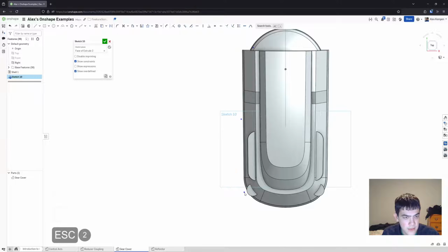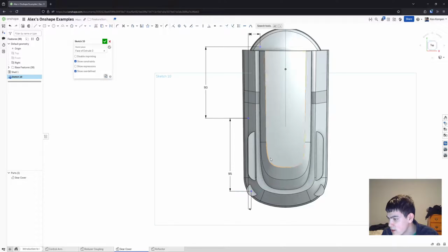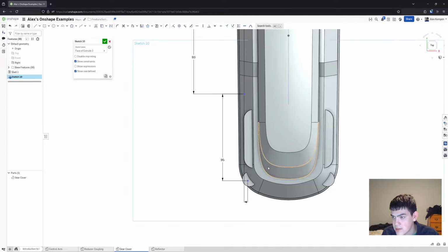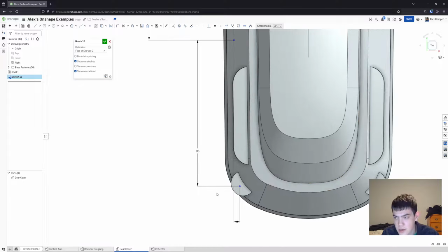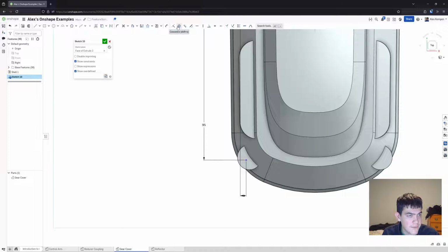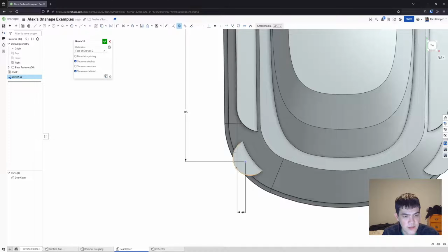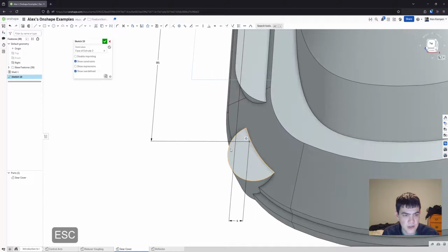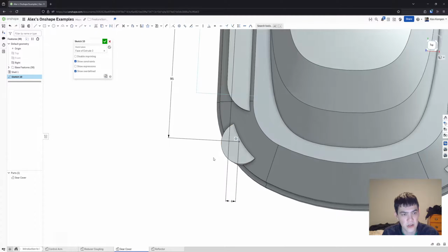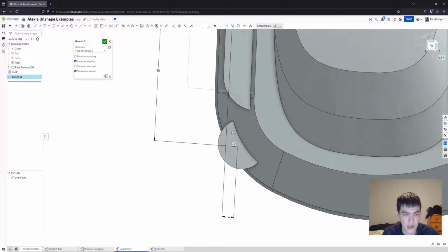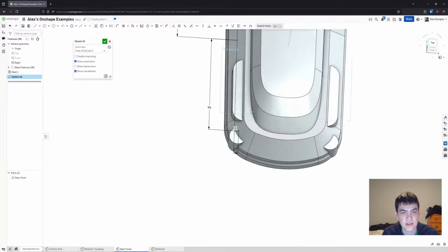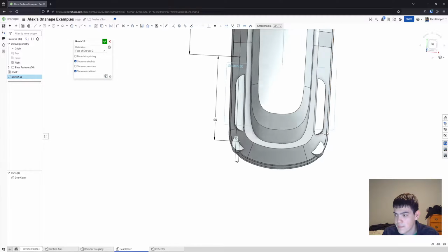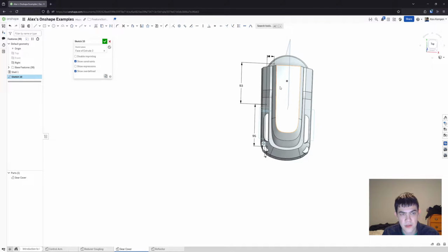Yeah, so now we have a set of points, and we can see they move together. So we just need to figure out how they're constrained to the origin. And here we can see they're asking us to make a concentric constraint. A concentric constraint just puts something in the center of a circle or arc. So here we're going to put this point in the center of this arc here. And of course that works because we can just use external geometry, like it's in our sketch. There's no requirement. Or you can constrain to stuff that's outside of your sketch. It's not a problem. Yeah, so once we do that, we can see we're fully constrained.